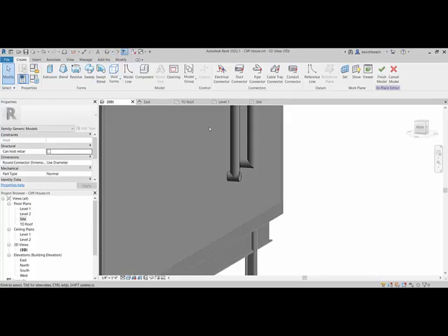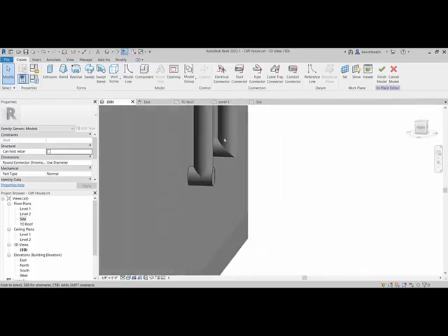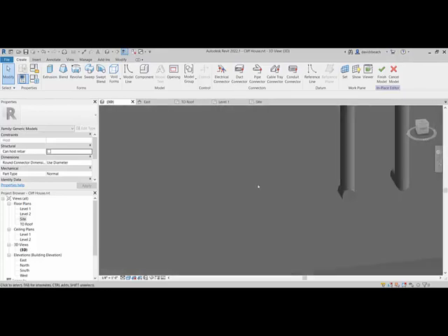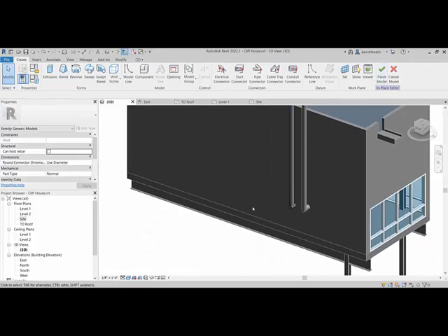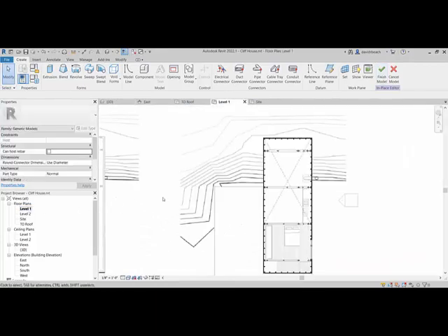So I can look at the geometry right here and know pretty simply by looking at this, that that is a 45-degree angle, right? If I've got two objects, 2 cylinders, same diameter, when they meet, they're going to meet at a 45-degree angle. So I could actually build something that sort of lops those 2 pieces off so I could connect them together a little bit more gracefully than what I'm showing on screen, right? And so void forms are something you're going to use often when you're building a little bit more complicated geometry. So let's do a little bit of void work off to the side first, just so you can see how this is going to come together.